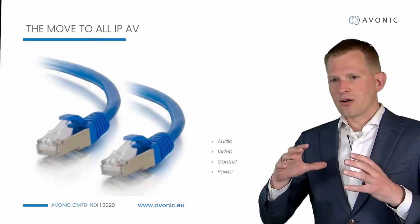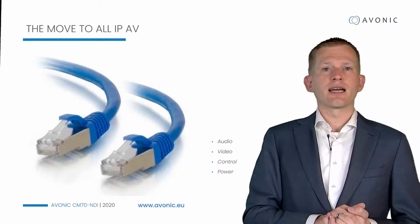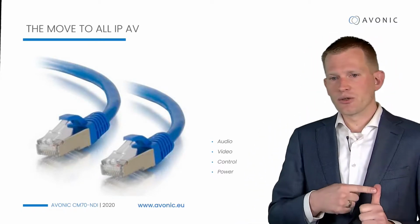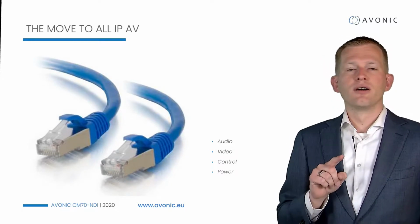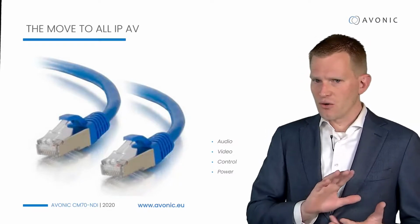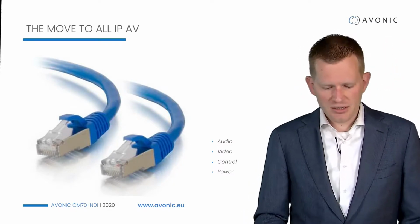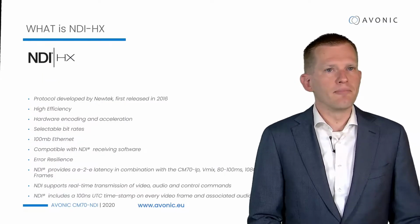Of course, you can combine all these different kinds of protocols into one. When you look at our CM70 NDI camera, it can be powered using a PoE switch. So you only have a single cable over which you can run audio, video, control and power. You only need a single cable and you're done. This makes the installation much easier than it was before. So this is where NDI HX really comes into play.